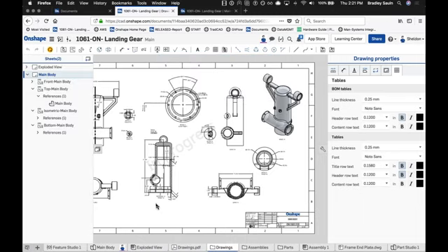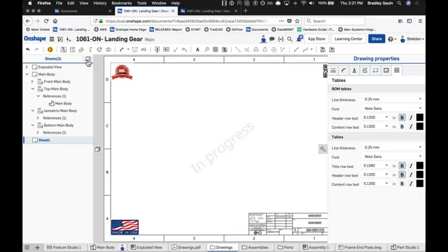When we are working in drawings, we always had a hotkey, at least in the modeling space, of Shift N to quickly go and rename things. So if I come in here and add a new drawing sheet, I can now just quickly press Shift N when I have my drawing sheet view selected, and then I can start typing into it right away. So maybe this is main drive shaft, if I can spell today.